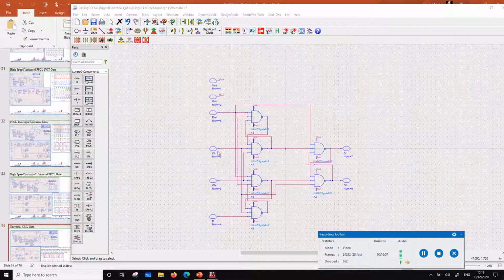So basically the rationale is this: if this clear is going to be low, then this flip-flop is going to have a high output, right, depending on the state, right? And if this is going to be low, then this is going to be high, so that will be set. So I think they are going to be preset bar and clear bar, right? But I am not going to just speculate. I'll just simulate and see.